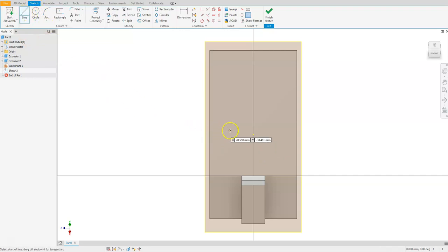Let's go ahead and draw a line, and I'm going to create this shape located here, and I'll draw it up here first and then I'll place it later. Once again, make sure that you're getting those constraints. So I'm getting horizontals, verticals, and perpendiculars locked on. I'll make sure that these two lines stay equal to each other by applying an equal constraint to them. Next thing I can do is I can determine how wide this is.